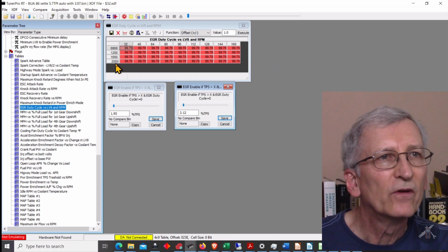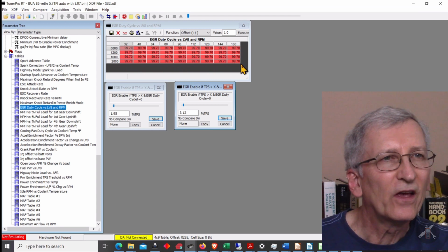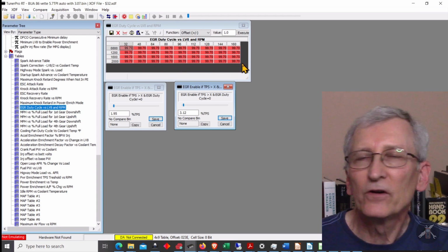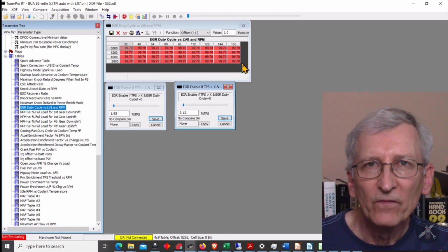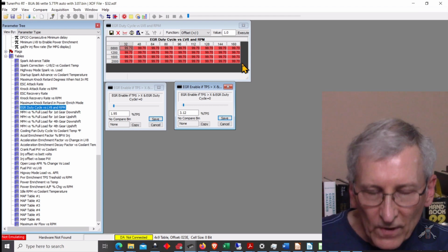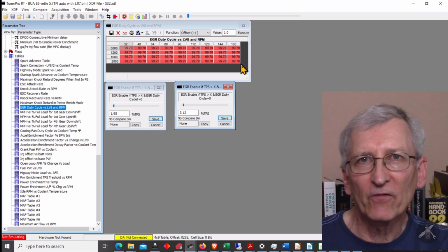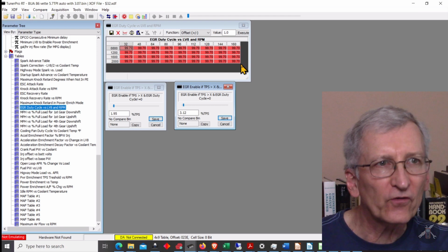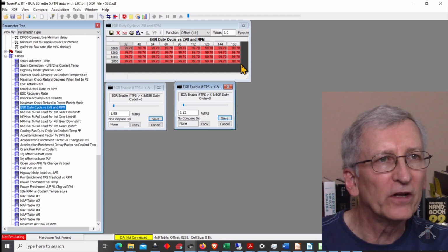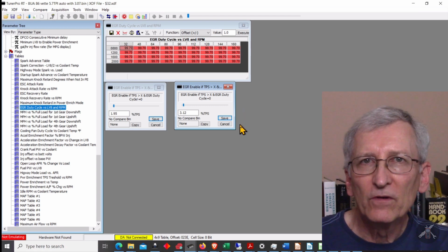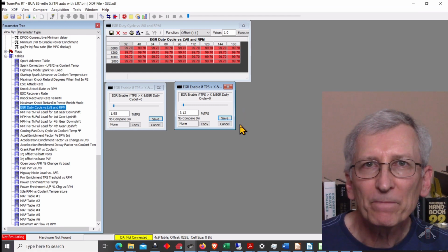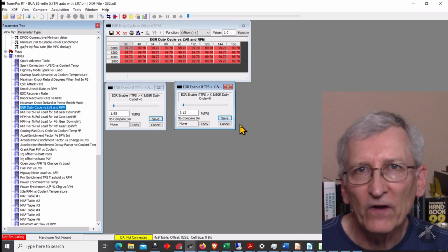It is from 800 to 2000, and it's 100%. So basically this is like what Mike would say, which is I either get 0 or I get everything. So here's an 86 Corvette, and it's calibrated just to open up that valve and let her run full EGR, whatever vacuum allows.